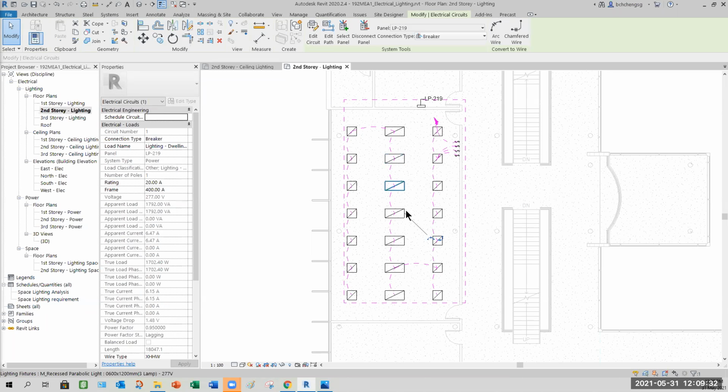Then you see below here, they have these two keys. These two keys show how you draw your cable. Because you have a ceiling, all these wires are connected using what we call conduit. Those flexi conduits, right? When you have a ceiling, you don't lay the fixed conduit. It should be flex.